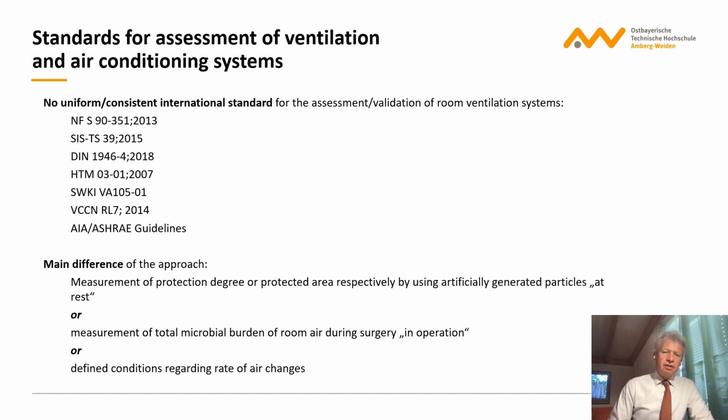In other standards, like the Swedish standard, the total microbial burden of room air during surgery is assessed in operation, whereas most of the Anglo-Saxon standards only look at air changes.